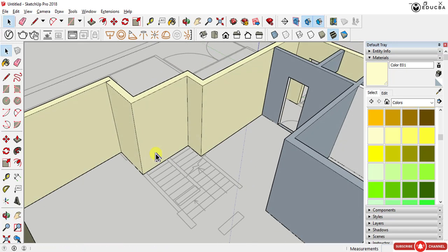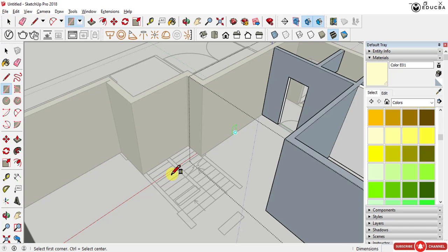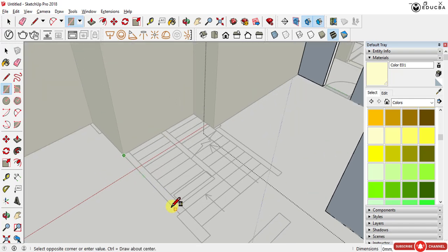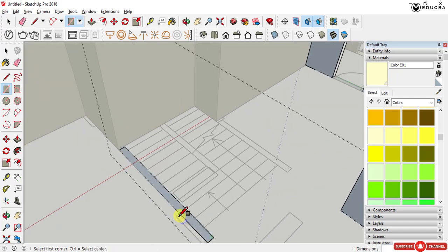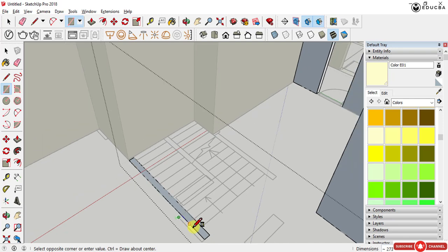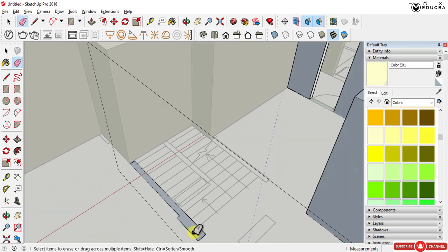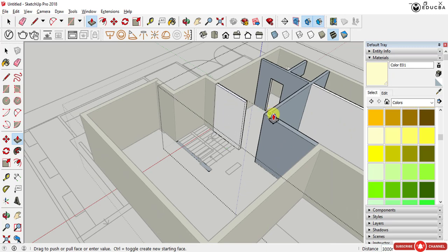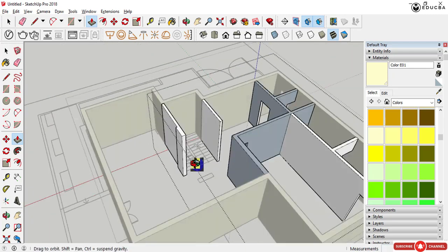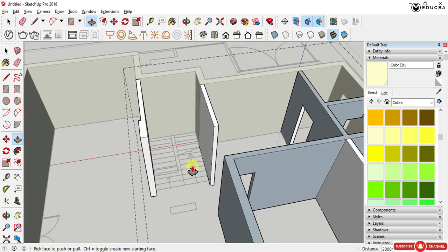Similarly, here we are going to just show a block. Let's go to this layer, make a rectangle right from the trace in the bottom, increase the column width, make another rectangle, erase this line, draw another rectangle representing this internal wall and pull them both to the same level as 3300, which is going to give us both the walls.